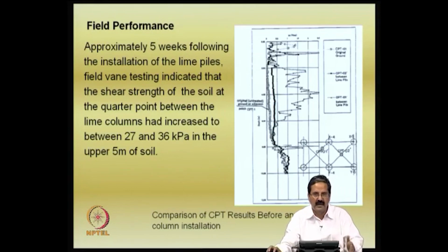Any contractor in the west, you will have all the people ready for it, like you need to have information on stone columns, PVDs, lime columns, whatever, all those methods, even geogrids, everything is available. Then you have to make sure that yes, the technique works in a given situation, and then try to come out with which is cheaper also, because if it is very expensive, and you should also have proper performance monitoring, like you must be able to do a test like this.